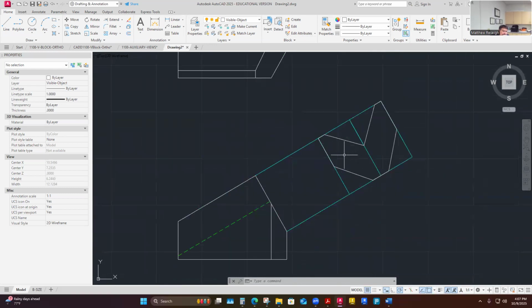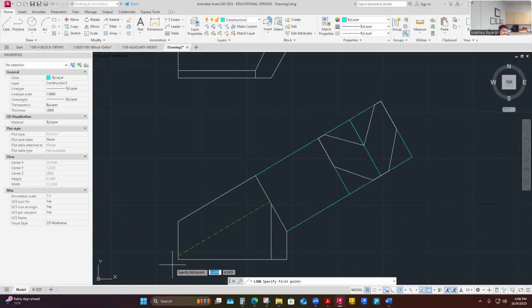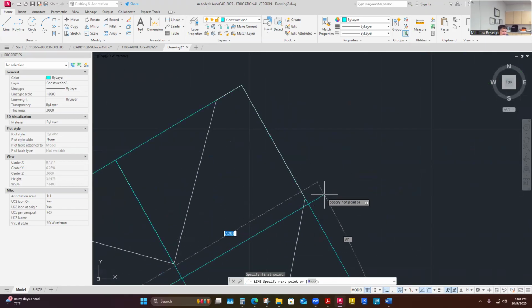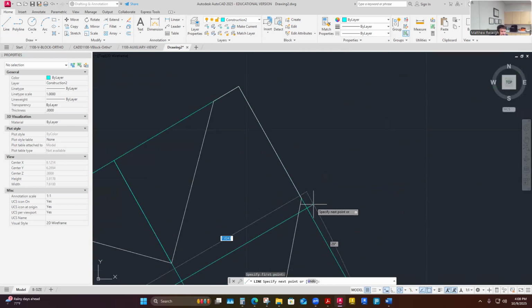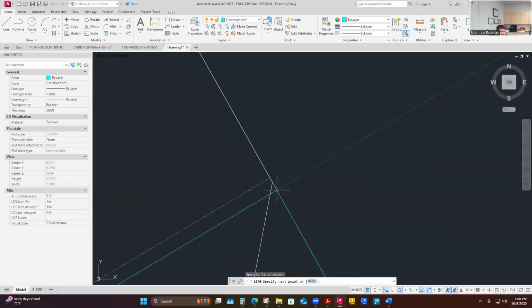Ah, yeah, I would. There was one thing that we noticed. I would see the back corner edge here, this left side bottom edge. The left side surface bottom edge is going to appear as a line across here, and so I can project that up and across potentially. I just got to be careful. I'm gonna stay on construction layer 2 and project. It's this point here. This would project over and across. I don't know where it hits. That's me staying on the 30 degrees, which is technically what it should be. I just want to be careful. I would snap it over, I'll snap it clear through the part.